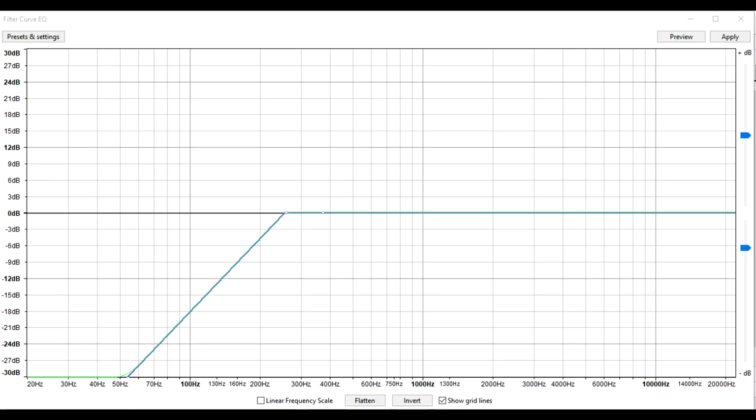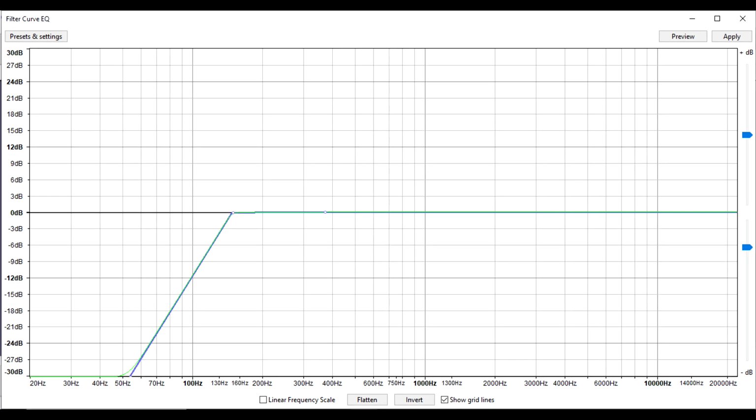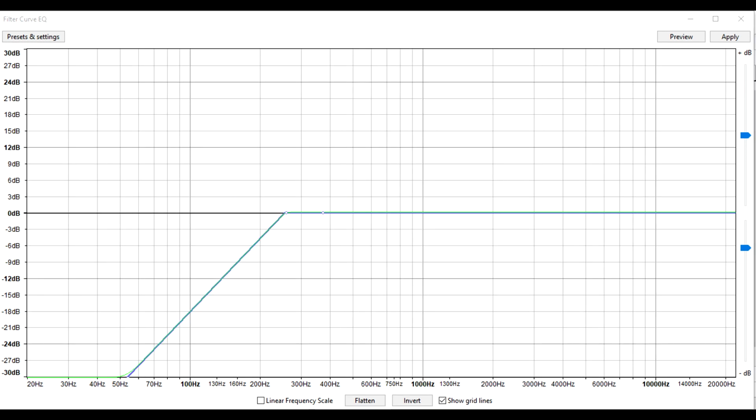Here is an example of my voice and my CNC machine sound recorded with a high-pass filter with a cutoff frequency of 250 Hz. Now I will adjust the filter to 150 Hz. The high-pass filter removes noise and adds clarity to the signal, but it also results in some loss of information.